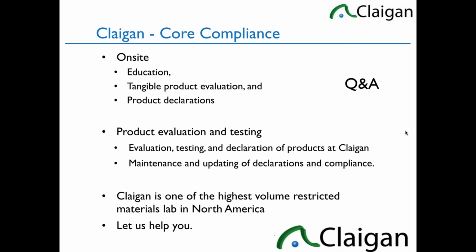So how do we define core compliance? We focus on what the core ones are for those products. Generally, it's RoHS, Prop 65, and REACH SVHC. Their core overlap is good. It's not complete, but it's good, and the differences between other regulations are often variations. RoHS 3 applies the phthalates at the homogeneous level. The SVHC is at the component level, so there are slight variations, but there's a tremendous amount of overlap, and you can do a lot to leverage it. So we look at the core regulations. Now, some product types have other things in their core regulations because of what they are, especially toys or children's products, which are slightly different, but still a tremendous overlap.